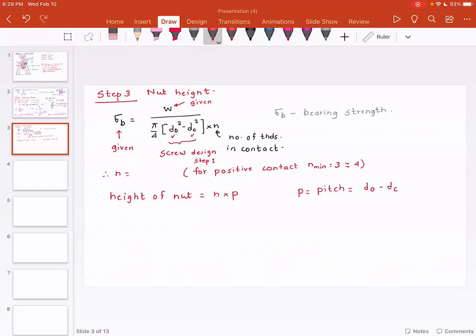And then what would be its implications on other components that get assembled with that shaft? For an example, what would be the bearing sizes? What would be the typical tolerances? What would be the type of fit? All this analysis gets carried out, and this is not just one person's job. Over a period of time, probably decades, these standards get developed, and then you have preferred numbers and preferred dimensions.